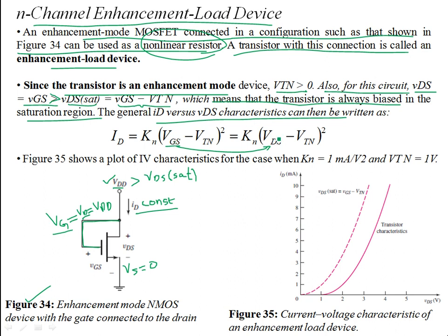As VDS is increasing, VTN is fixed, given it's the device parameter, the threshold voltage of the device. Kn is the conduction parameter. Those parameters are fixed. You see that ID increases with VDS, so there is a quadratic behavior of ID versus VDS. The transistor is on because VDS is greater than VTN, and it is still in saturation, but the current is now increasing with VDS quadratically.